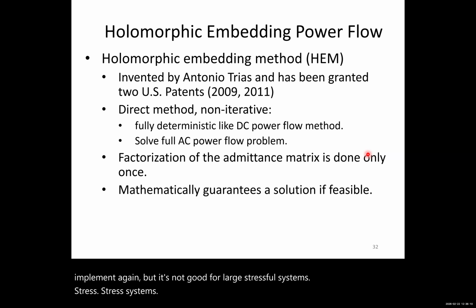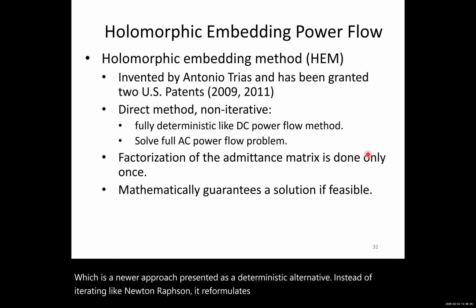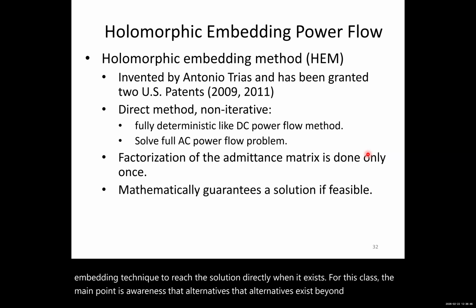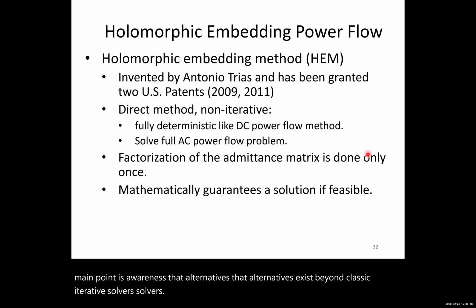Now, the holomorphic embedding method, or HEM, is a newer approach presented as a deterministic alternative. Instead of iterating like Newton-Raphson, it reformulates the problem using a mathematical embedding technique to reach the solution directly when it exists. For this class, the main point is awareness that alternatives exist beyond classic iterative solvers, but again, we are not going to go deep into them.